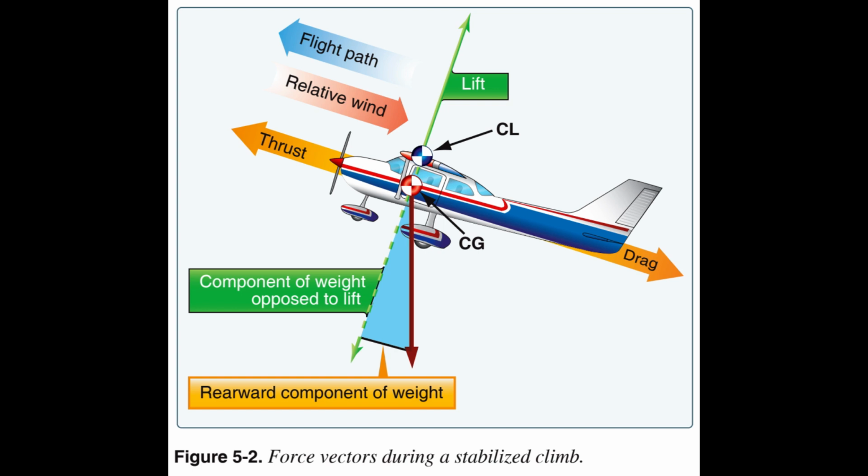If in level flight, the engine power is reduced, the thrust is lessened, and the aircraft slows down. As long as the thrust is less than the drag, the aircraft continues to decelerate. To a point, as the aircraft slows down, the drag force will also decrease. The aircraft will continue to slow down until thrust again equals drag, at which point the airspeed will stabilize.